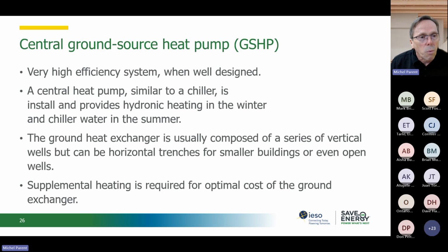You will do a test well to make sure that the ground has proper characteristics for your ground source heat pump. So always have test wells, unless it's a really small system and they already know the characteristics of the ground around that system. Very efficient. You will cut your heating cost by 3 in this case. You will likely cut your cooling cost by maybe 20%. They can be more efficient than a chiller, but it's very close because a chiller is a very, very efficient machine. The ground source is very efficient in cooling, but like I said, nowhere as efficient as it is in heating.